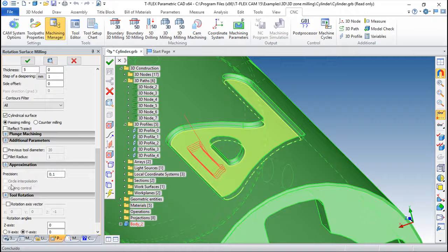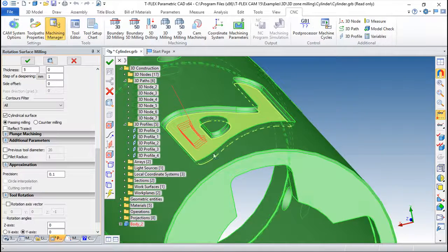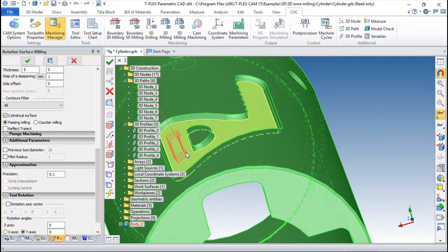In this particular case there is no circle interpolation because the movement is a little different, and we can connect this also to rotation of the axis, but maybe it will make a more complex toolpath, so we need to use this carefully, and we need to have the post-processor properly defined to take advantage of these rotations.